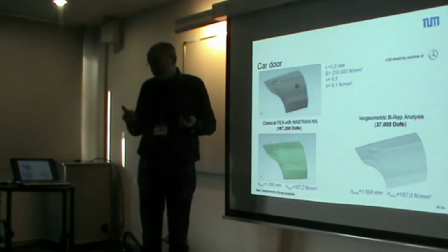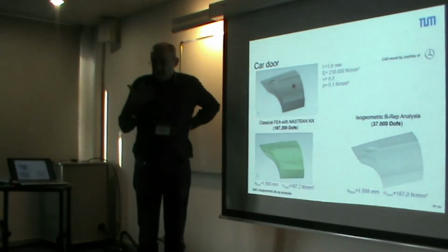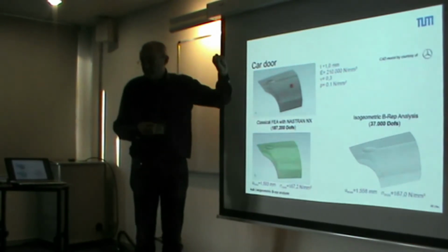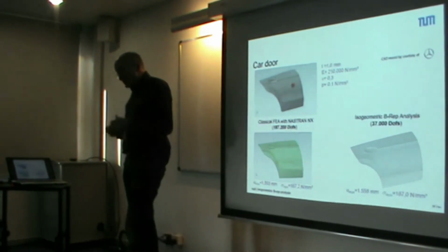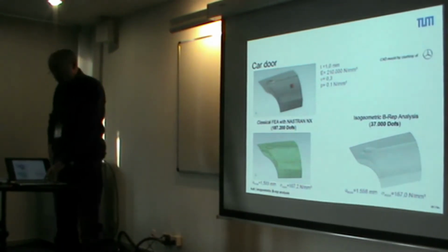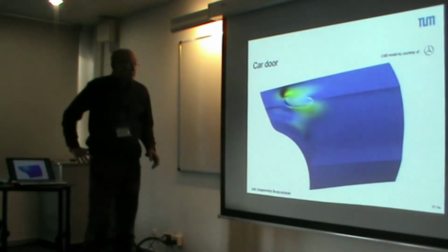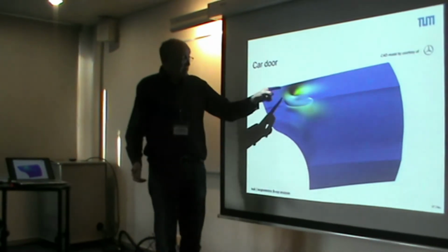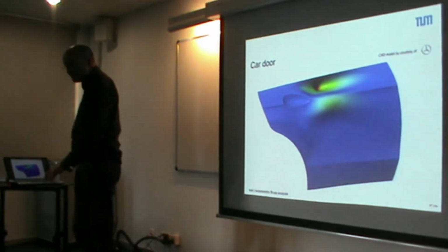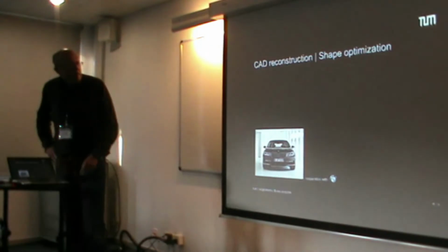Of course, deep drawing is a plastic problem, but it was surprising for me. They have so much knowledge and databases available that they're able to do linear elastic simulations with typical, efficient, effective load cases to get this information, whether it might be deep drawn or not, from a linear elastic simulation. The idea is just having the CAD model available, doing this test on the CAD model, getting the result from that, and going on with the generation of your model.